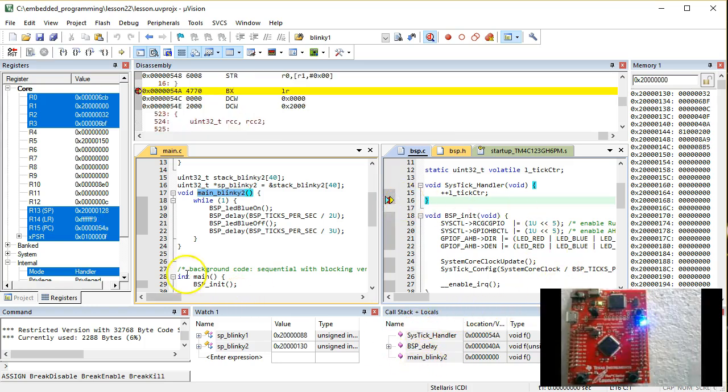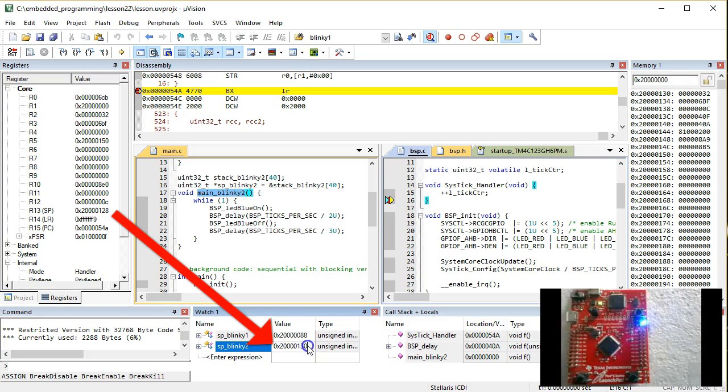Your manual procedure of switching the CPU context is to break at the end of the SysTick interrupt, copy the current value from the SP CPU register into the stack pointer variable corresponding to the currently executing thread, and to copy the other thread's stack pointer to the SP CPU register. Please note, however, that you no longer need to mess with the stack content in memory.